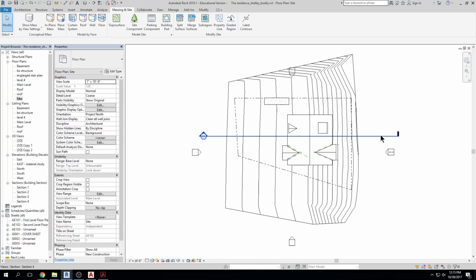You want to be somewhat realistic, or reasonable, in it. Make it somewhat larger than the property you're creating, the house. Put some slope to it. It could be very slight, right? If you want it just to slope gently and not deal with it, great. You could add some topography to it if you want to have a different look to your property. But play around with it, see how you like it, check out the functionality. But part of your midterm will be that you want to add a topo surface in there, okay?